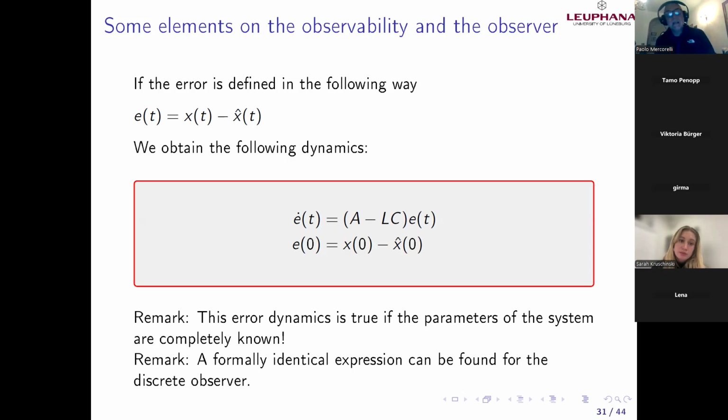I am building an observer in infinite time, even though, do you remember, observability is defined in finite time? It seems to be a mismatch, but believe me, we can also build an observer in finite time. It's not the case here because it's too complex, in general, in a bachelor course. For the students who attended my classes in dynamical systems, for instance, the sliding mode observer is in finite time.